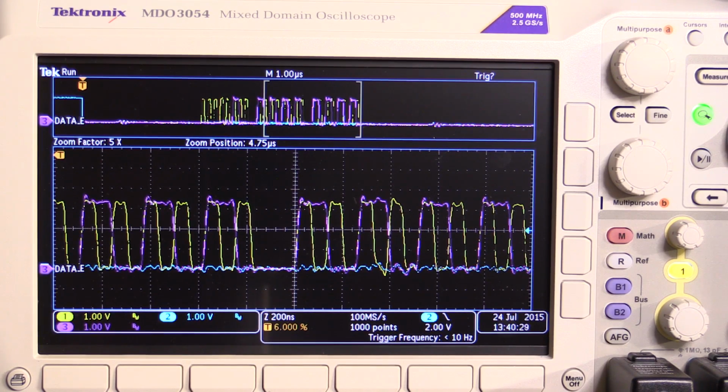One of the problems with, obviously, and I've done previous videos on time domain reflectometry and stuff like that, is the length of wires and having connections and various other things connected with reflections on the end when they're not properly terminated. Things like that can have a huge impact at high frequencies. So of course, the higher speed that you clock your data lines at, the bigger problems you're going to have when it comes to reflections and corrupting your data. I don't know how far you can push flying leads like this, and maybe I'll do another video on experimenting with it. But for now, I've just upped it to 20 megahertz instead of 10. So let's just see what this looks like.